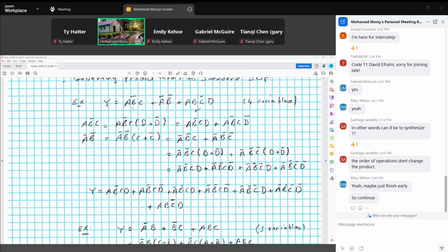So how do we convert from this form to standard form? Let us take the first product term here, AB inverted C. We try to put it in another form, so we use our knowledge and properties of Boolean algebra to reach our goal. We need to get from non-standard form to standard form. So what is missed here? Variable D. Okay, so can we multiply this term by D plus D inverted? Can we do that without changing anything?